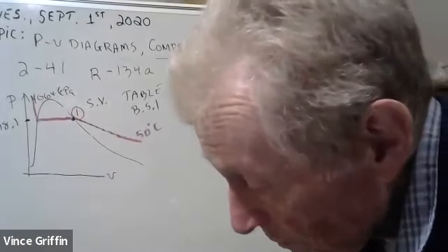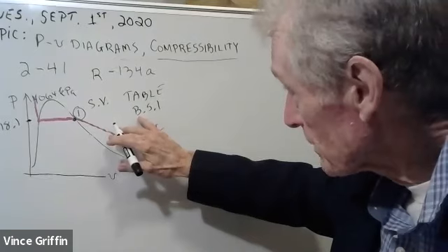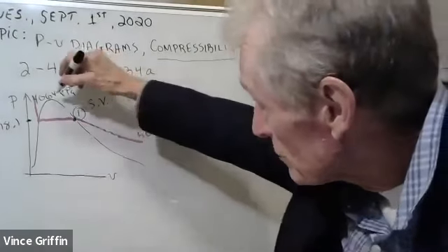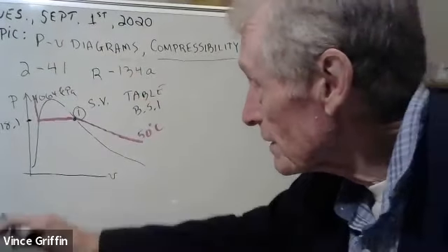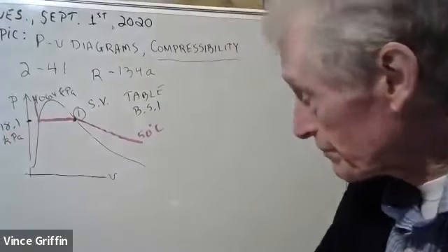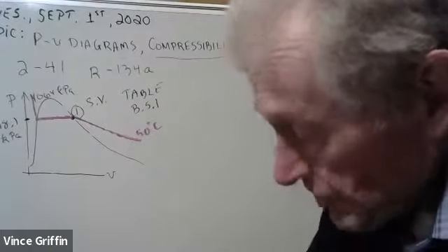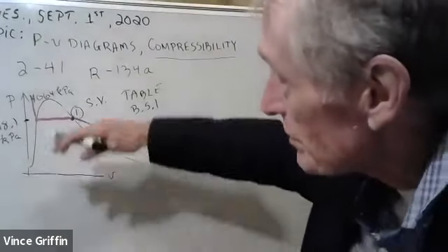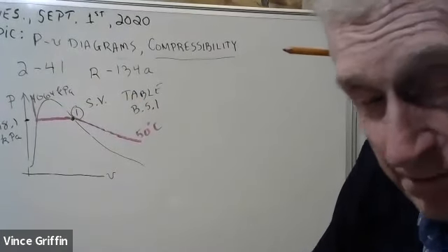Now who am I talking to? This is Taylor. I'm gonna go look it up in my electronic book too and make sure I can find the same value. Yeah, find it. Get your electronic book, table B.5.1, and you'll see that the very top of the dome is 4,064. But where we are is 1318. That 4,064 is at the very bottom of the table, but it's at the top of the vapor dome. See, it's just opposite. You understand?